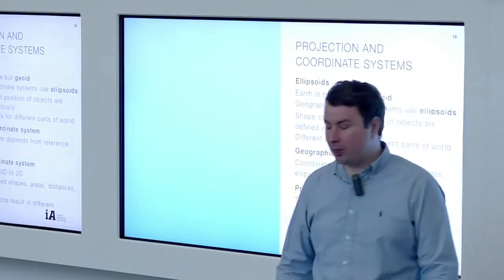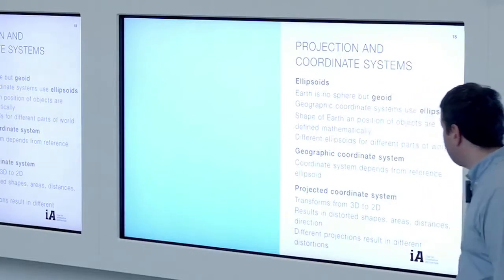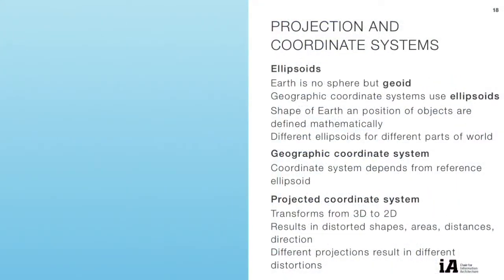The only problem is that the Earth is not just a sphere, it's a geoid. That makes life very complicated. Usually, you don't experience that if you're working with architectural plans. The site is just too small, but everywhere you have the bending of the Earth's surface, and that shifts everything a little bit.